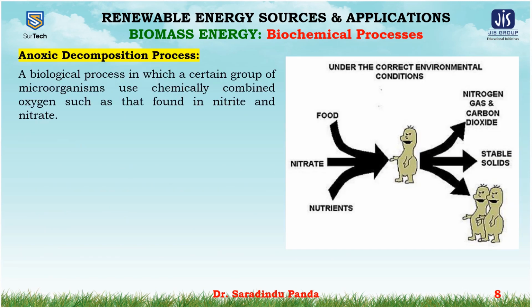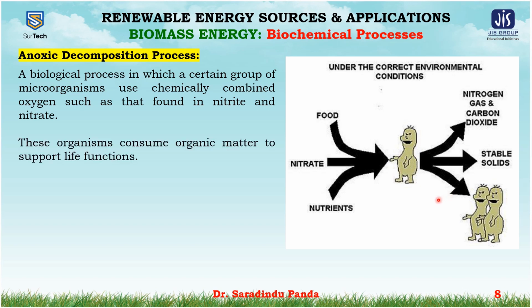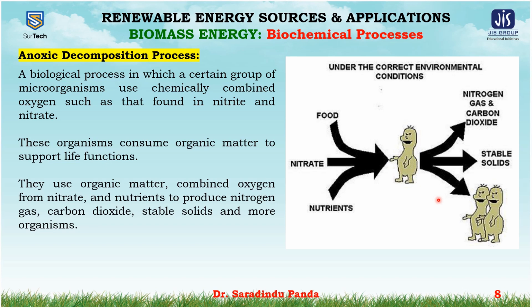Anoxic decomposition is a biological process in which a certain group of microorganisms use chemically combined oxygen, such as that found in nitrite and nitrate. These organisms consume the organic matter to support their life functions. They use organic matter, combined oxygen from the nitrate, and nutrients to produce nitrogen gas, carbon dioxide, stable solids, and more organisms.